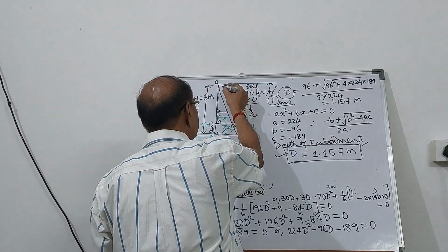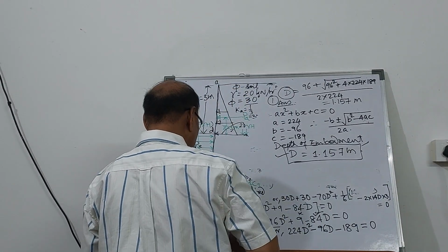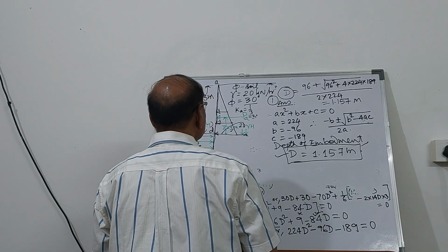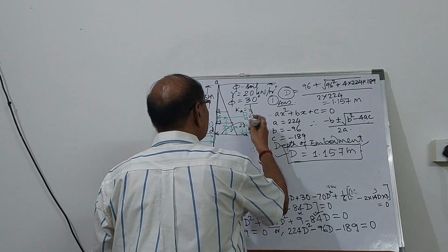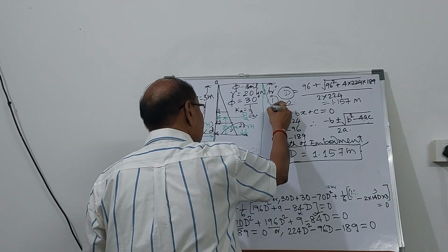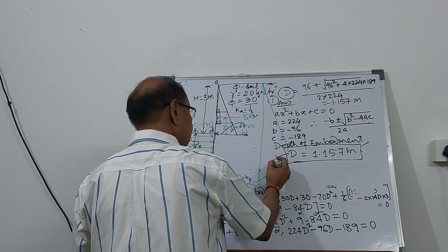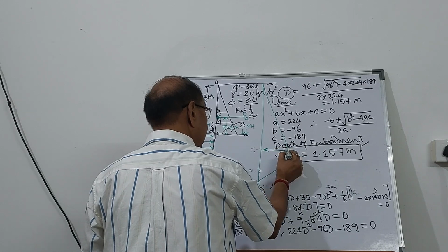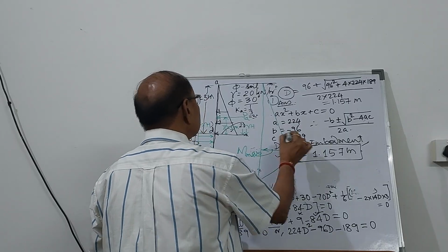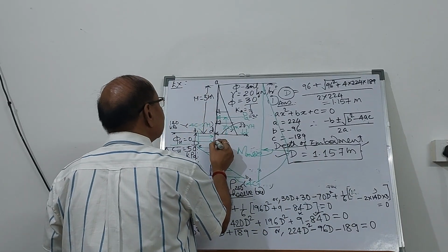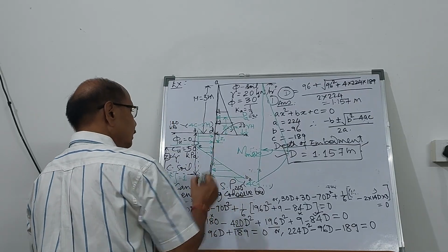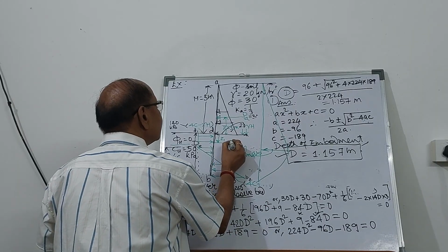Now, if you want to find out the maximum moment, the locus of maximum moment is going to be like this. So if you draw the locus of maximum moment across the height, it is going to be like this. So the maximum moment will be in this part. Let's say at some distance Z1, the shear force is going to be 0.